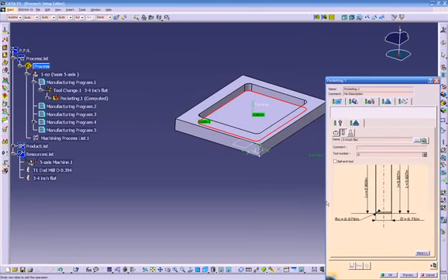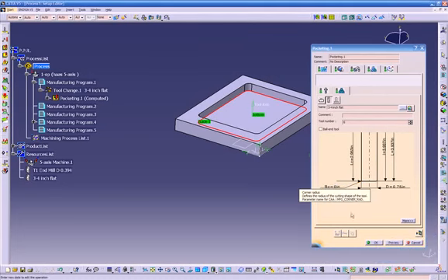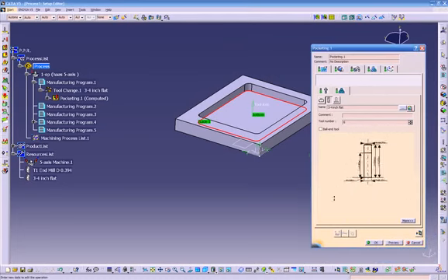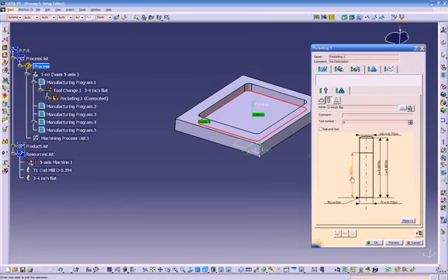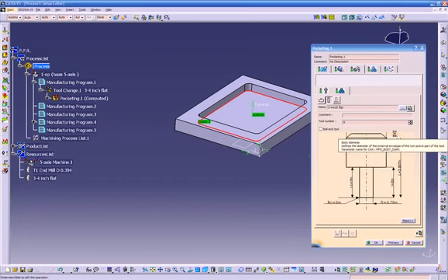And you can customize it. Even my operation, even though I said it's a 750, for some reason it puts this radius in here, but you can double click on it and make it 0, make it a sharp corner. And you get your tool over here, customize. You can put the tool length in here. Let's make it 2 inches, and let's make the holder 2.2. That's a standard size.